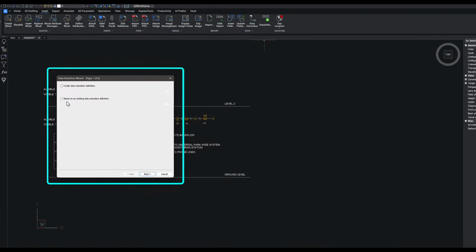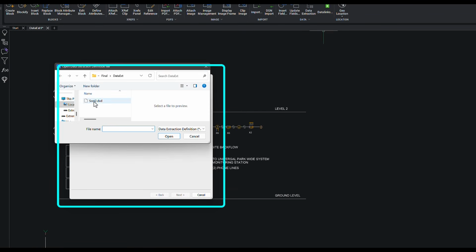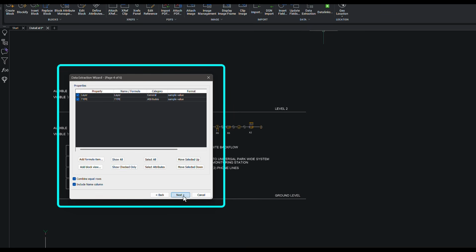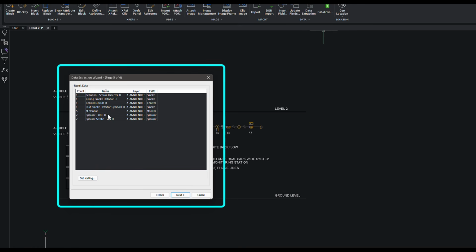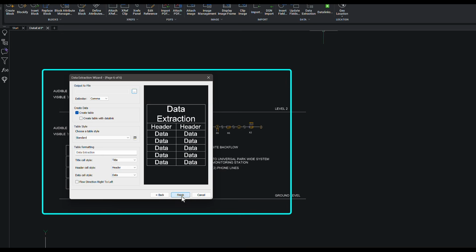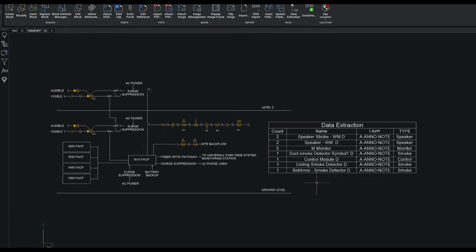The Sort Data page in the Data Extraction dialog lets you organize your data before you output it. You can choose one or more fields to sort by and pick whether each one sorts in ascending or descending order. The sorting follows field priority, first by the main field, then by any others if there are repeats. The order of the columns in this dialog decides the order in which the rows will be sorted. This helps keep the final table neat and easy to read.